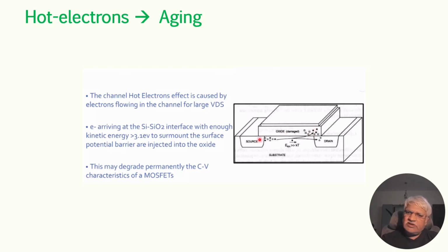So you can think that this is hot carrier injection. This is one more phenomenon, and this will happen in the cold temperature. This will lead to delay degradation, and this is what is happening in the NMOS.